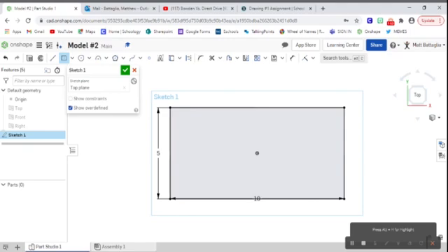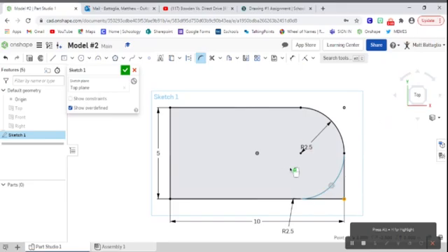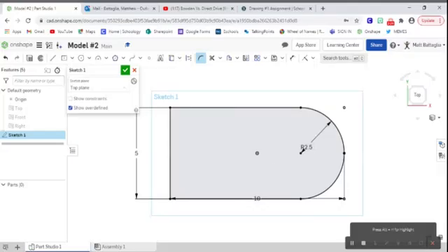The very next step I'm going to do is start by putting a sketch fillet in. To avoid doing a fillet later on, I'm going to get it out of the way now. I know that my fillet is going to be pretty sizable. In fact, it is going to be a 2.5 inch radius. You can see I have one on this side and one on that side. And now we're left with that nice rounded over front.